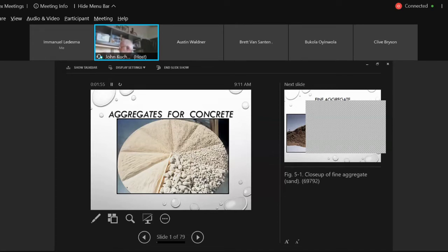We're going to quickly look at the City of Winnipeg specification, because we have to find the parameters that we're going to be designing for. The slump, the air criteria, the strength criteria the City of Winnipeg requires for their concrete. But anyhow, aggregates, key. If your aggregates are no good, your concrete mix is no good. That is the key. If you've got good, selected, processed aggregates, meeting grading specifications, durability requirements, porosity requirements, you'll be able to mix good concrete. That's key.